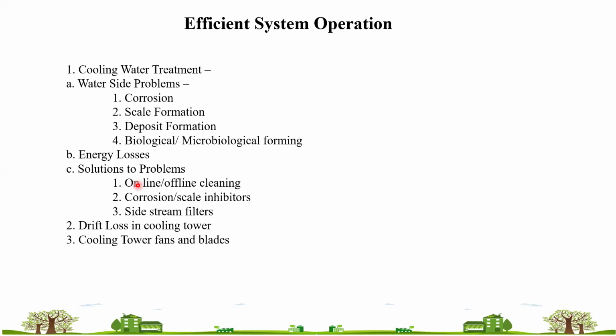And you are saving 2 kilowatt of energy here, meaning around 20 rupees per hour, and you are losing 1 kg of product there. So your 1 kg of product is much costlier than your 20 rupees. That's how your process, their design, and your audit has to be combined in any energy auditor.